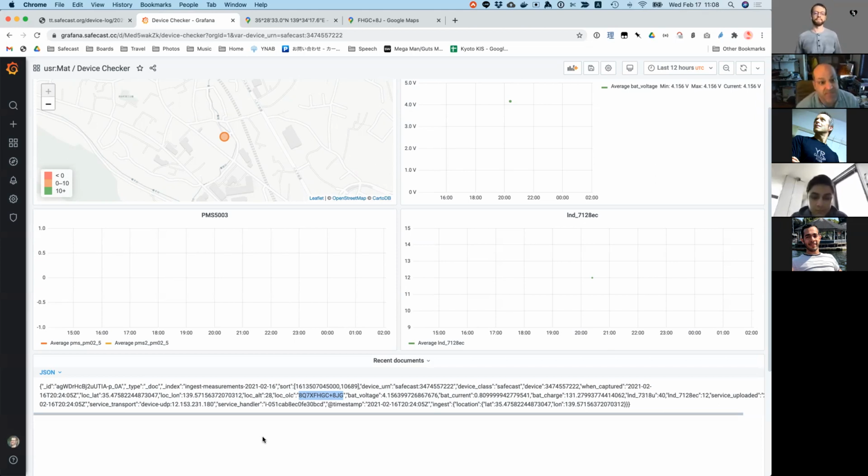If you haven't got a good sight of the sky, or have unlucky satellite arrangements, the GPS module can take more than 2 minutes to get a fix the first time, because every time is a cold start. But if I power its RTC, it'll have a better prediction about where it should be, and it should lock much faster. So I can do that.